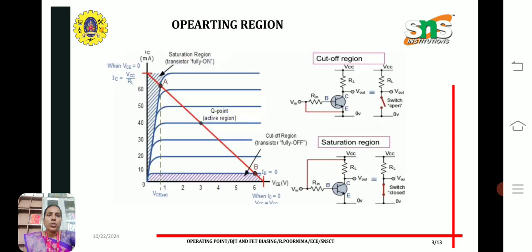So in the operating region, there are three regions: cutoff, saturation and active region. In the cutoff region, the transistor is in the off state, and in the saturation region, the transistor is fully on. In the active region, the Q point is at the center of the load line, in which the transistor acts as an amplifier. For this we need to bias the transistor with the emitter base junction forward biased and the collector base junction reverse biased, so that the transistor acts in the active region.